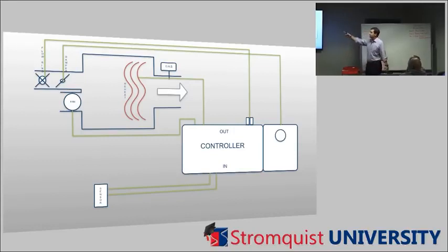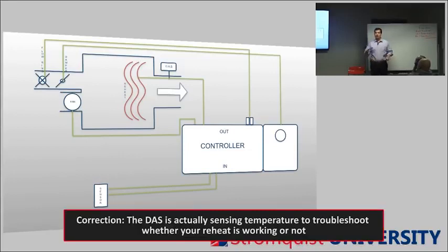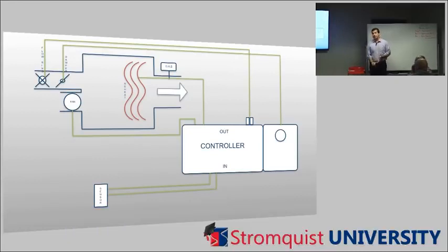Well, if you see that your fan's on and your damper's wide open, maybe your reheat strip's on because you're wanting heat, but still something's not quite right. Well, you look at your discharge air sensor and it says 0. Well, you know something's not working. Fan's not working, or the air handler down line's not working. So you can diagnose a lot of stuff right from your desk. These days, right from your iPad or tablet or smartphone. You can stand right underneath it and start pulling up things and trying different things before you ever grab the ladder, which goes back to productivity savings, right?